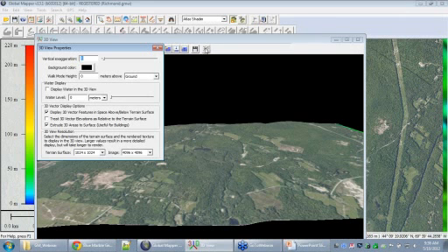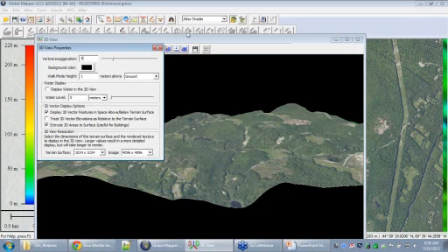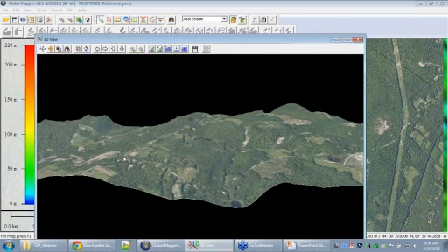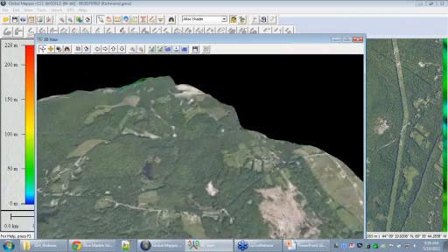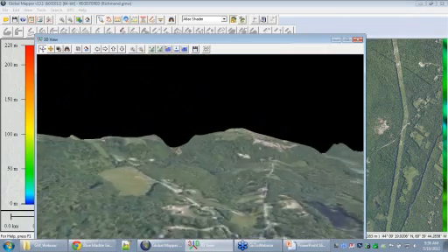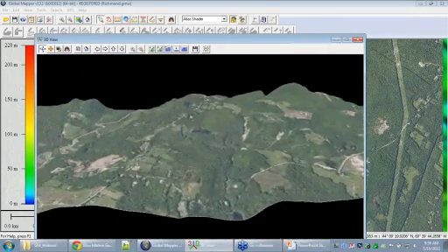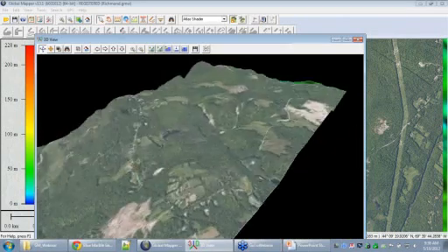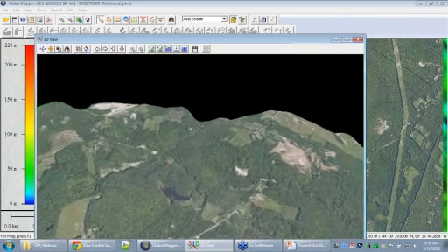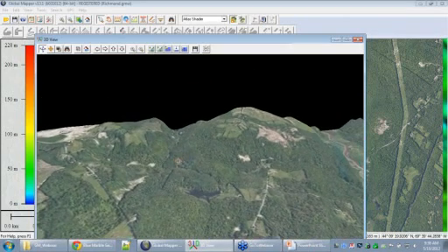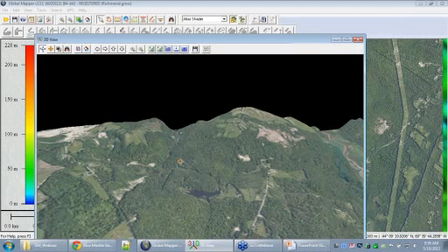So what I'm going to do here is go back into our 3D view properties. That's the little gear button on the far right of our toolbar, and let's bump that up. I'm going to make the exaggeration up to about 5. This data is located in Maine, nearby where we are. I'm just going to bump up the exaggeration so we can very clearly see some of those different hills, and we can pretend we're somewhere a little bit closer to the foothills of the mountains with this data.